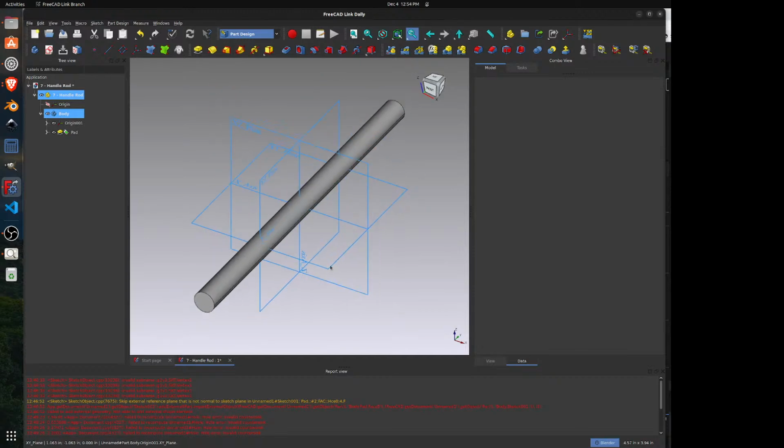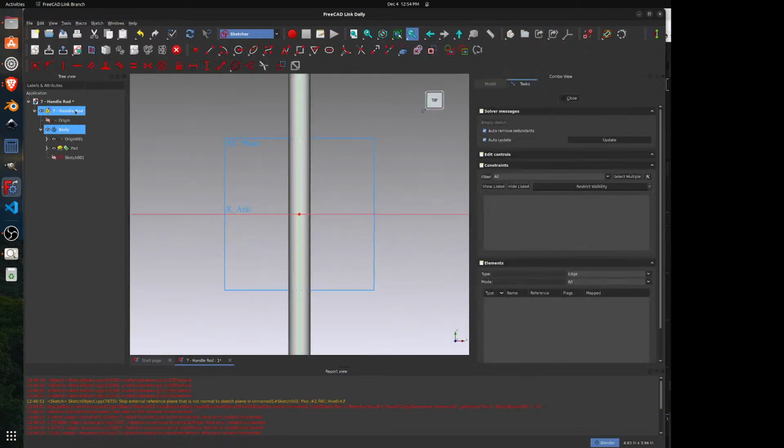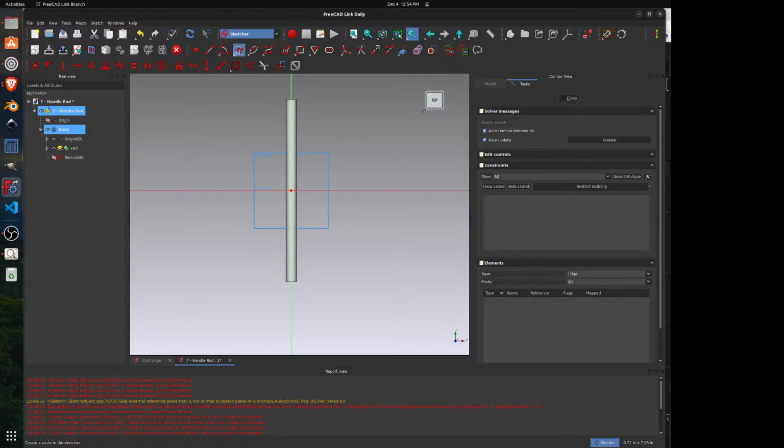And so then the next thing I'll do is I'm going to add these holes in, and to do that, I'm just going to do them as an extruded pocket here rather than a hole. And the reason I'm going to do that is I can pick now the XY plane, create a sketch, and now I can draw two circles. They're a little hard to see, so I'm actually going to just hide that pad for a second.